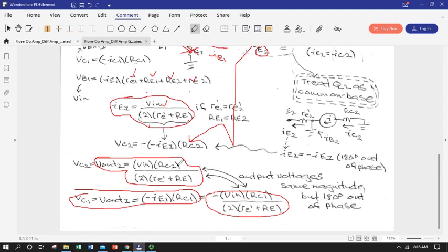Boom. Lots of red circles here. The double arrows are important because they show that our outputs at both 1 and 2 are the same, Vn, Vn. The two collector resistors, which should be the same, the AC little emitter resistors and our big biasing resistors. All of this is the same except for the direction. So I would advise you step through the math. It's really easy algebra. We can get an expression for Vout 1 and 2 that are opposite in phase but the same magnitude. So that's the big takeaway.